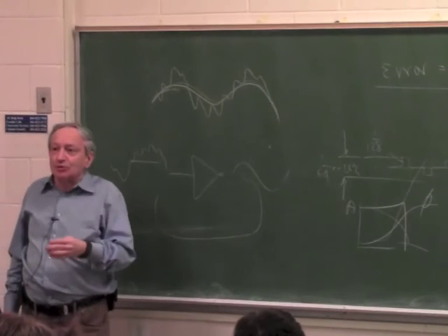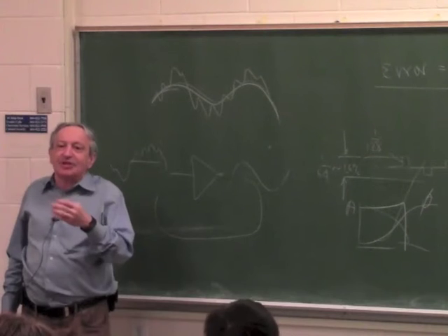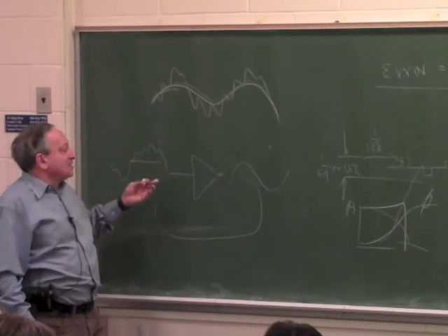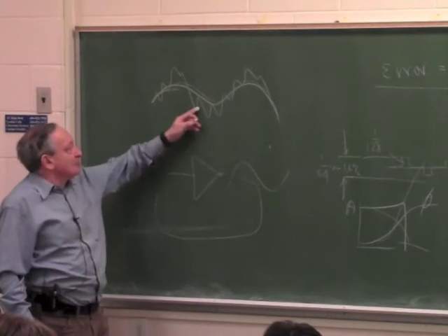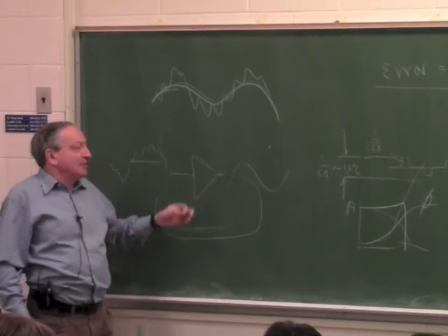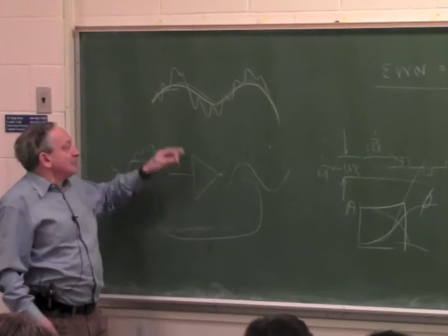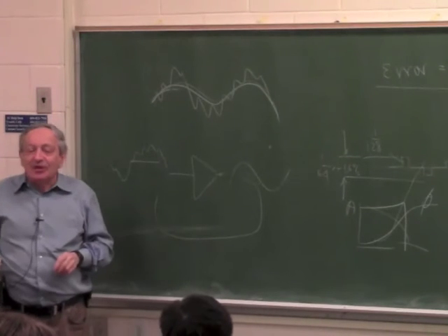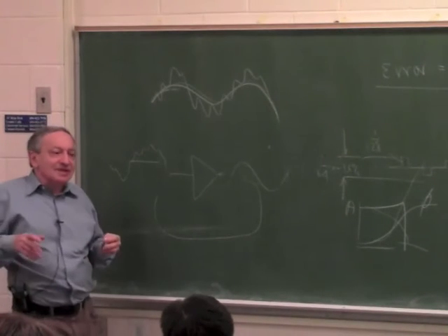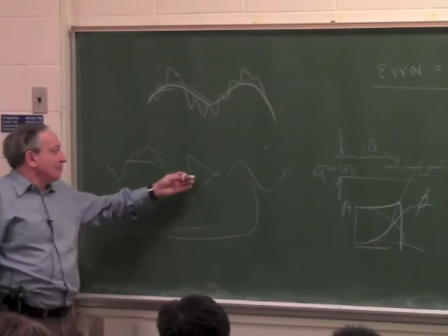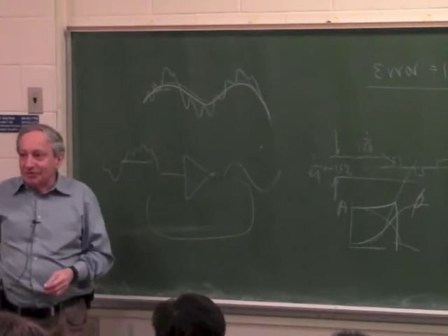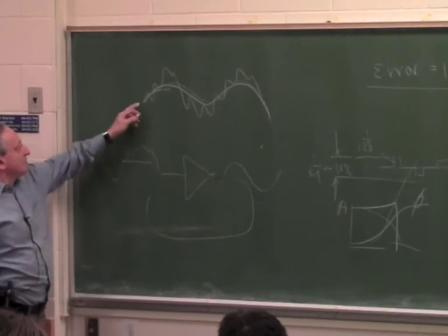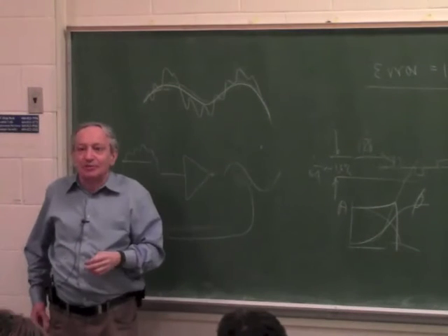But that's a consideration too, because actually you are right, because most amplifiers have more bandwidth than they need, but it can start oscillation even if you don't put in noise. If an amplifier has more bandwidth than you need, even without the noise, positive feedback can develop. Positive feedback doesn't need the noise to trigger it, right? Okay, but you could say that you answered a different question. Why don't you allow too much bandwidth in the amplifier? Because of positive feedback. That's correct. But why do you want to get rid of all this noise even if the system cannot respond to it?